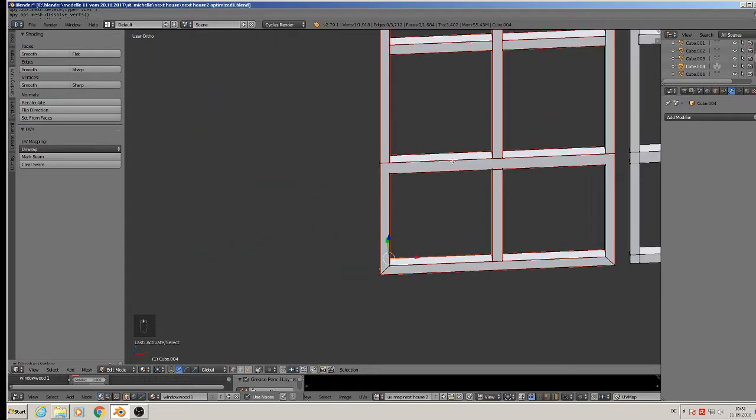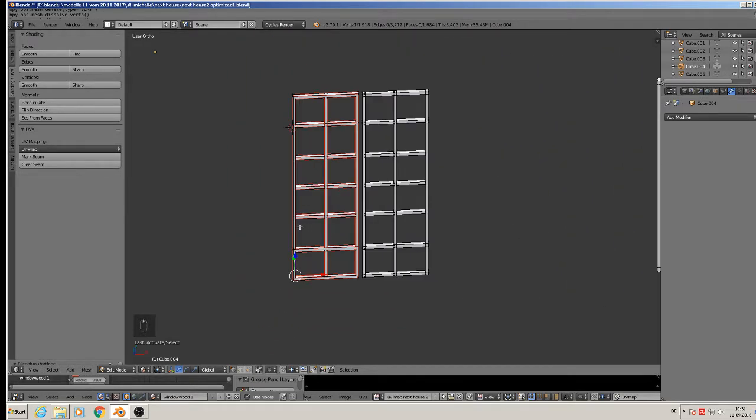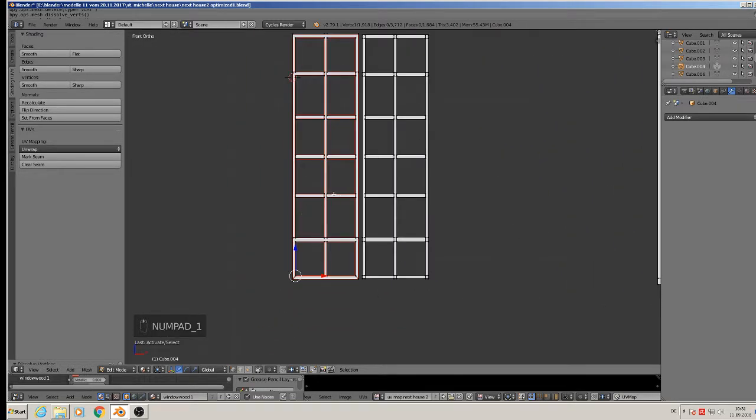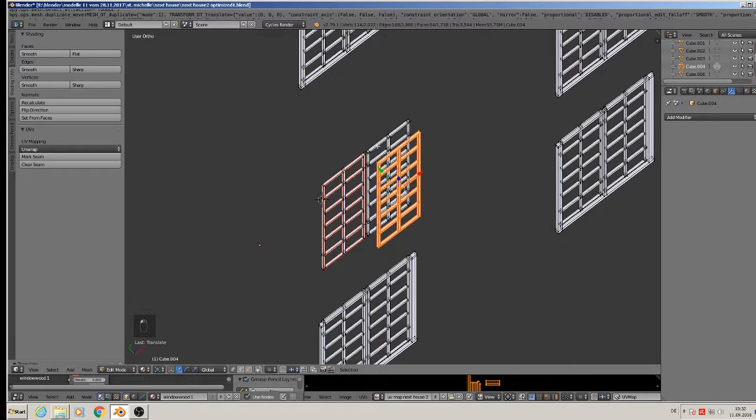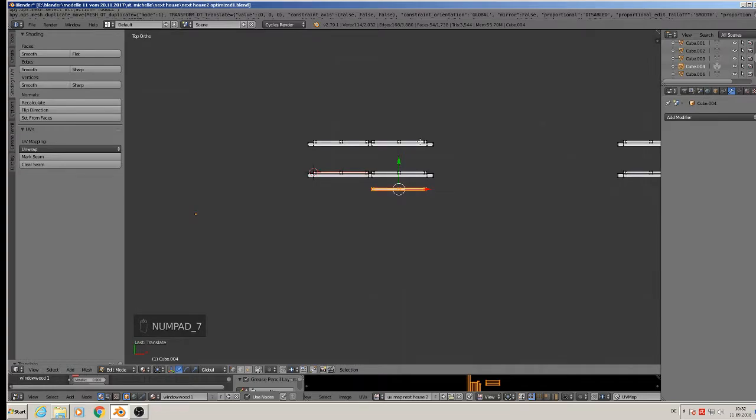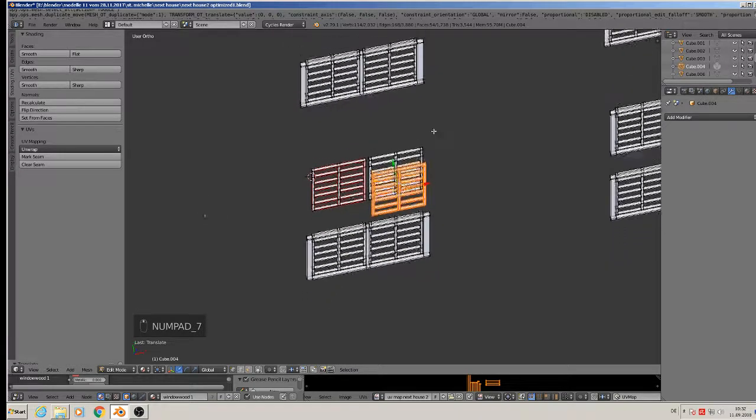Good. Again. So with background selection and word selection and border selection, we take now that whole thing there, Shift D, and place it over the other. Then we bring it more in front so that we can delete the other one, the imperfect one.